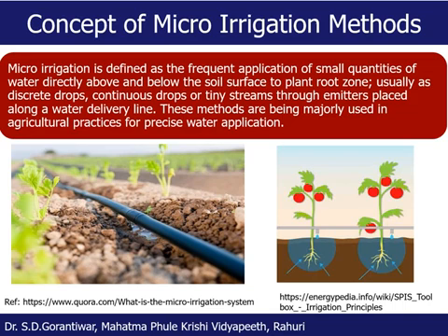Okay, so during the period of 2 weeks, what happens? As I am applying a large quantity of water today, the moisture content in the root zone for the next 2 to 3 days will be near saturation, which is also not the desirable condition. Then as the plant root takes water, the moisture in the root zone will be depleted.